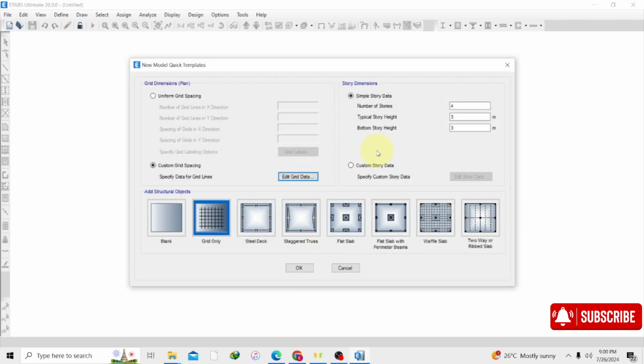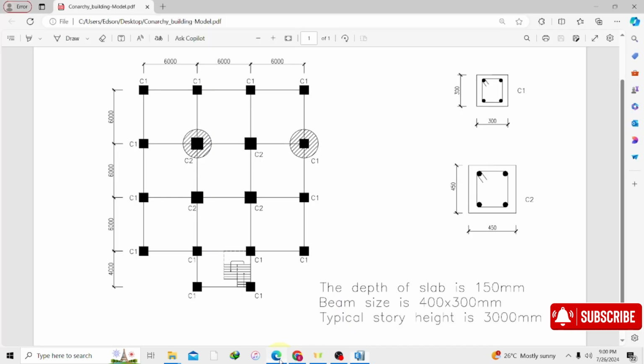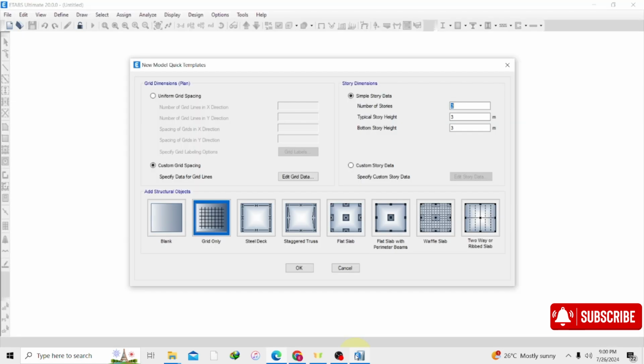So let's come to our story dimension. We have to change our values here. So the number of stories, let's stick with 2 stories for the meantime. But as we go on through the video, we are going to increase our number of stories. And our typical story height, with the info at the bottom, we know that the story height is 3,000 millimeters throughout the entire building.